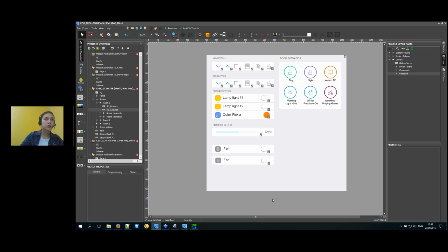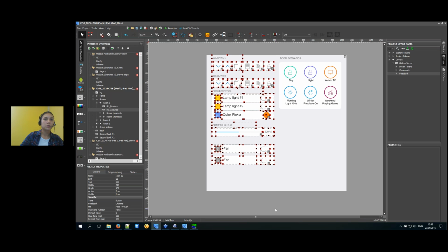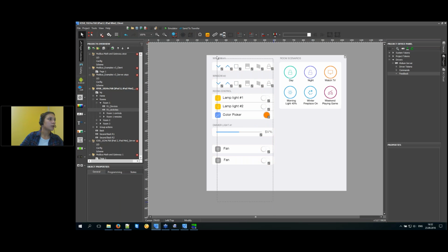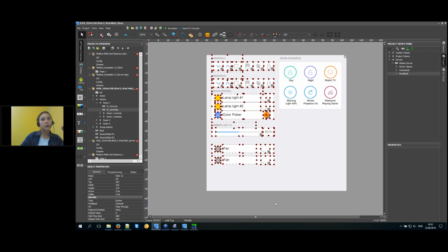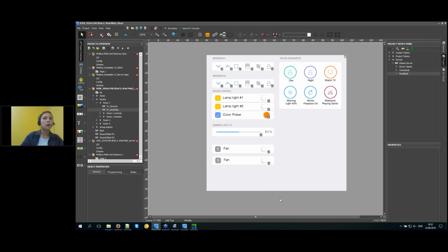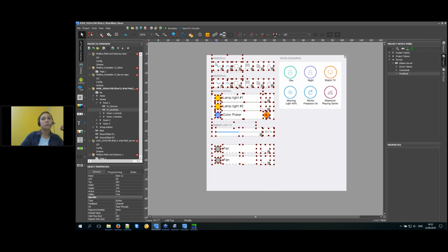If your PLC does not support Modbus TCP, if it is RTU or ASCII only, you can install some physical gateway from Modbus TCP to RTU and connect to it via Modbus TCP anyway.